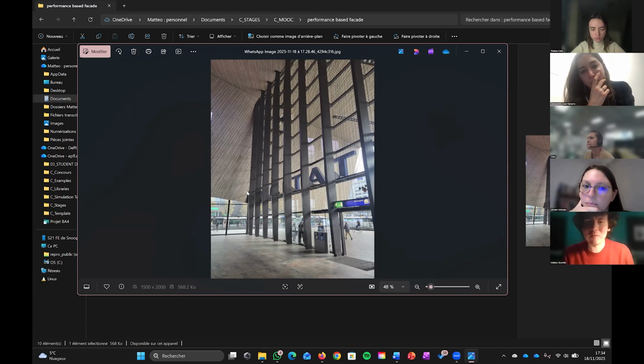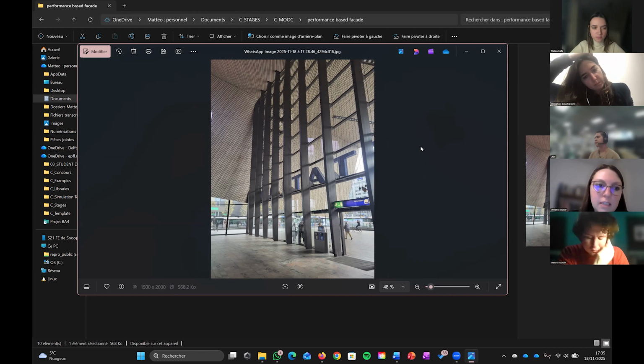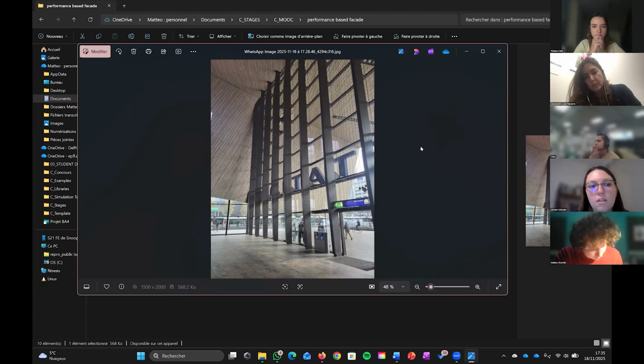Maybe. I assumed that in my assignment, and that's why I took this example, because it was nice to show that we can reduce some of the thickness at different levels depending on the loads or moment. But then I thought maybe it's load bearing for the entire roof, and that's what we can't really detect from the pictures. But the load transfer is mainly the same. So maybe we have additional loads from the roof itself, but at least when we are looking at the wind loads, for example, the load path is exactly the same as for the examples that we showed before.